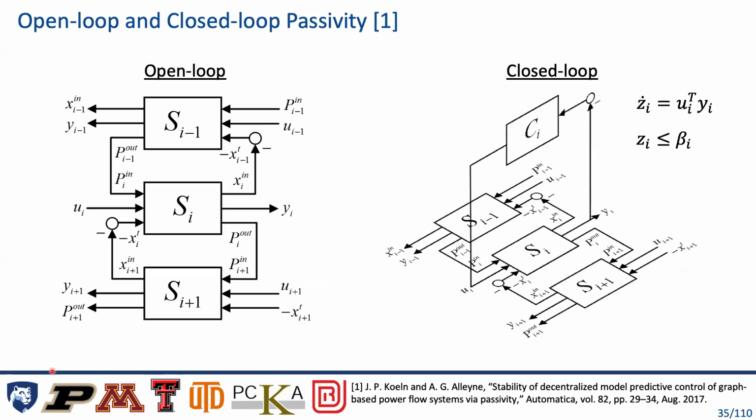Passivity is a nice way of looking at the stability of your system, and it has this nice compositional property where if you have 2 passive subsystems in negative feedback with each other, passivity is preserved. So using that, if we can demonstrate that each subsystem within our system is passive, and then show that all connections between subsystems or systems are through a negative feedback connection, then we can guarantee that our overall system is also passive. So that would be in an open loop sense, just to prove something about the open loop properties of a complex system.